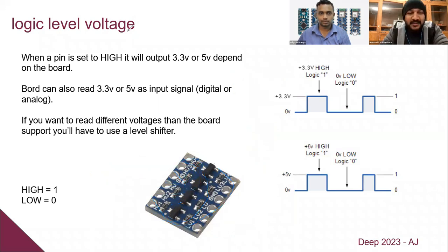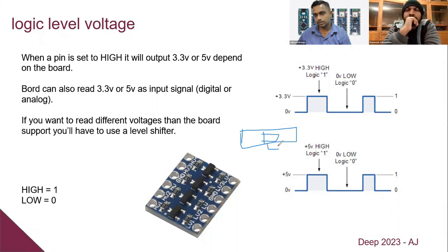Awesome. And the original question I was going to ask is, is this like a buck converter? Oh no, this is not like a buck converter. A buck converter is generating a PWM signal and chopping off some part of the voltage signal, right?